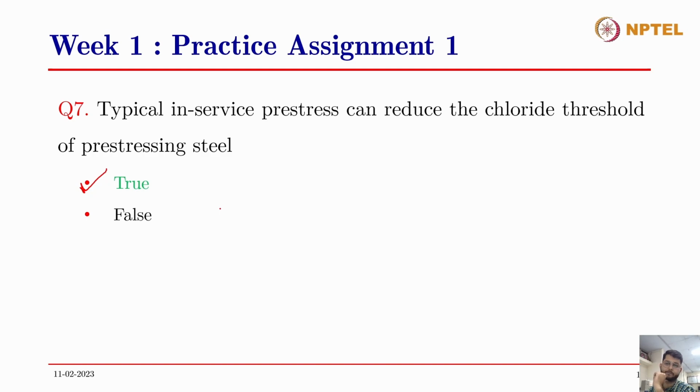Right. Okay. Thank you, Dr. Satish. Yes, as he has rightly mentioned, the presence of previously induced stress can always increase the risk of corrosion, because even with a lesser amount of chloride than the chloride threshold, which essentially is the reduction of the chloride threshold, the corrosion can take place.